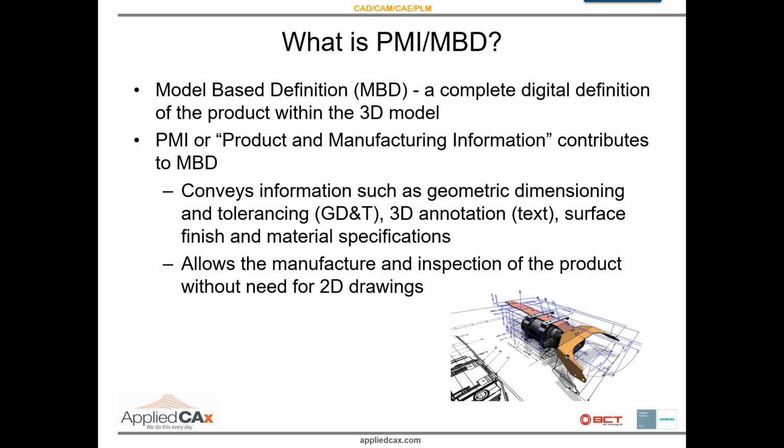So what is PMI, a model-based definition? Well, PMI is NX's application of model-based definition. It allows you to document your model in 3D with dimensions, notes, process specifications, finish, material, and the like, allowing you also to place GD&T, geometric dimensioning and tolerancing, as well as use that PMI in downstream applications. We'll cover a little bit of that too.